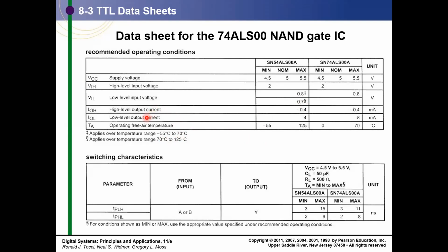If you see the currents, these are output high current and output low current. The minus only means the reverse direction. High is sourcing and this is sinking. This is only relative to the direction of the flow of current. If the current flows inward, then it is positive. If current flows outwards on the output node, it is negative.